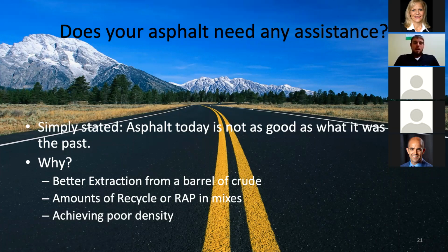And while that may not be the case, there's just multiple different processes that have changed, including the manufacturers are getting better at extracting a barrel of crude. The recycled content has been increasing year by year. And then also with that increased RAP, sometimes it's even more difficult to obtain the proper density that a job's called for, and poor density, as everybody knows, usually leads to premature failure.